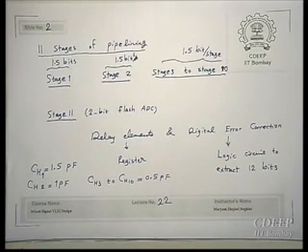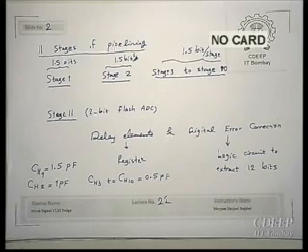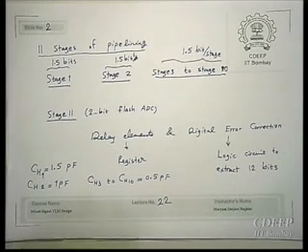They also mentioned that if you had used 1 picofarad for all stages, definitely you would get better performance. But here they are reducing these capacitors, and they say the amount of degradation you get is acceptable for them. Therefore, they have reduced capacitors to 0.5 picofarad from stage 3 onwards.